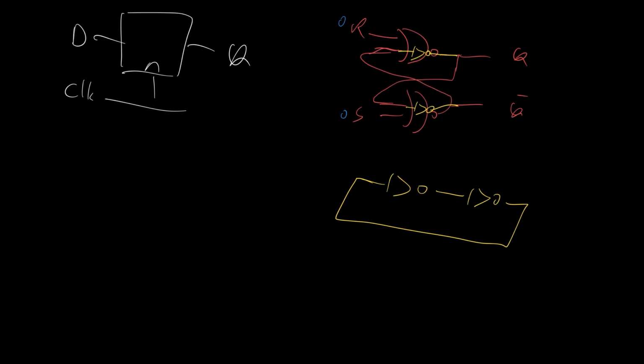And no matter how you make a flip-flop, whether you use transmission gates or you use the way we learnt in lectures, where you start off with an RS latch, then make a D latch by putting some combinational logic out the front, then using a master-slave, 2 D latches in master-slave combination, you can end up with a D-type flip-flop. So it doesn't matter how you build it, basically you've got 2 inverters at the end that are doing the latching, and we'll analyse this circuit now.